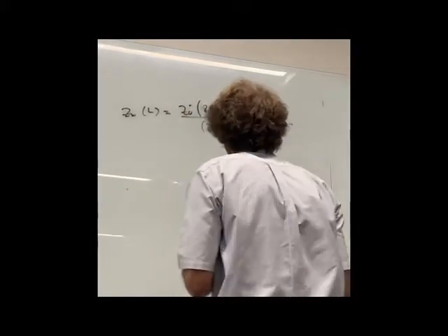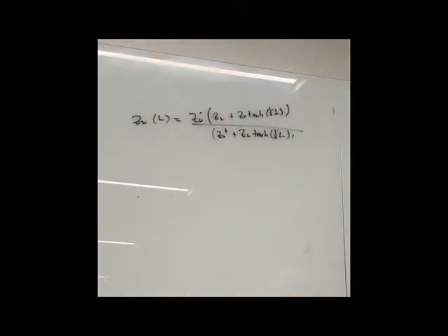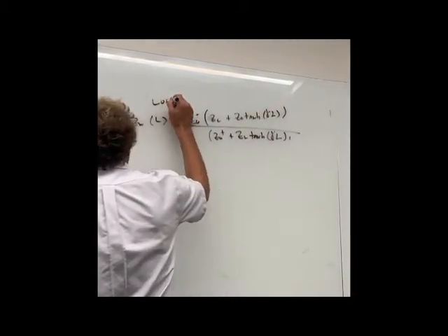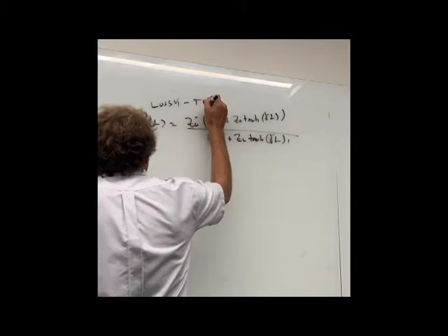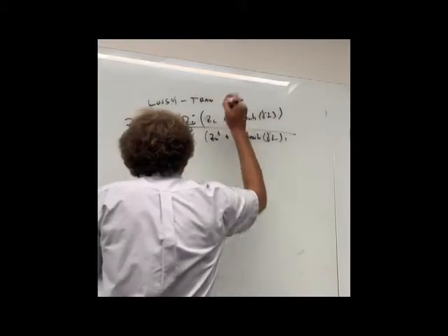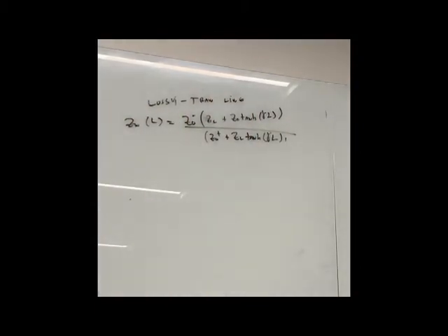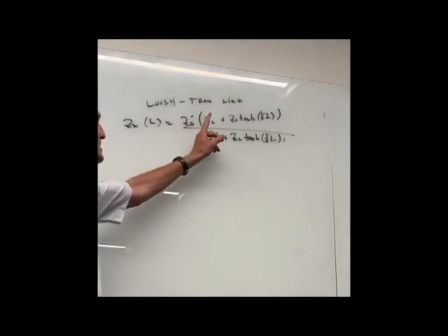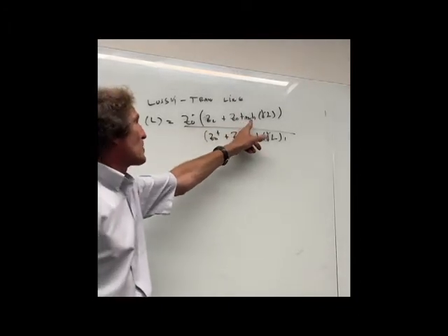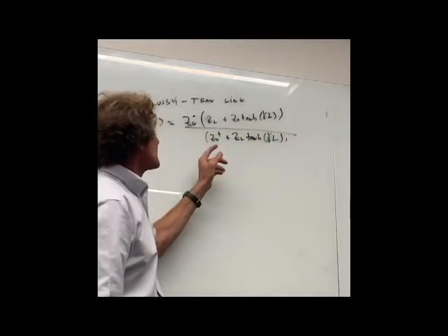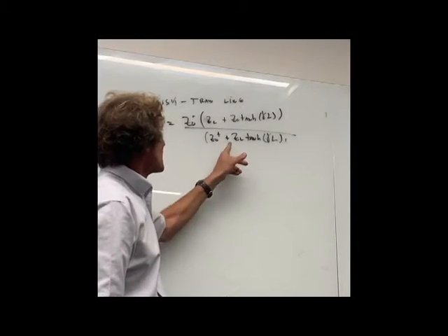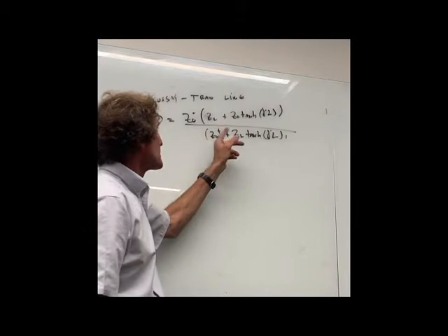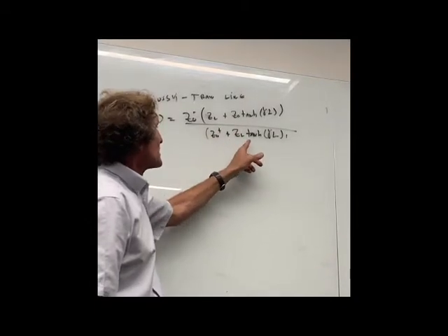Now this is in his book. This is the formula used for the lossy transmission line. You can just put lossy T line. If you have your books, you can take a look at that. That's Z0 times ZL plus Z0 hyperbolic tangent of gamma L, divided by Z0 plus ZL times the tangent of gamma L. In other words, the load and characteristic impedance are interchanged.